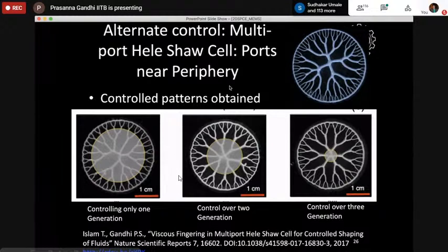Okay, so still I have not talked about how we create these structures out of these fluids, which are ceramic slurry based, where you have a ceramic powder mixed with a photopolymer. Once they are formed, they retain the shape because these ceramic particles have some friction between them, and that gives these fluids a yield property.